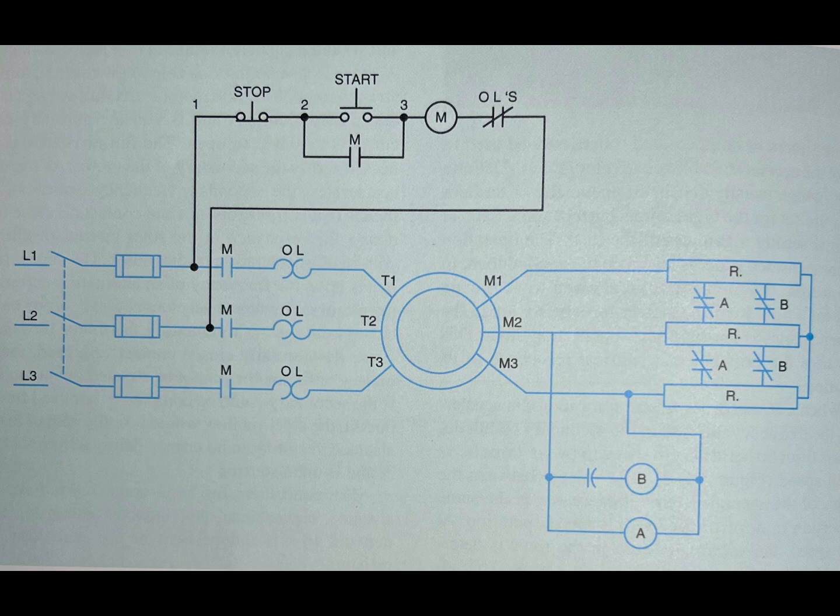If the secondary could be completely removed from the circuit, the electron flow would take the path of the least resistance, resulting in no energy being delivered to the coils A and B upon starting. The controllers for large crane hoists have a resistance, capacitance, and inductance control circuit network that is independent of the secondary rotor resistors.